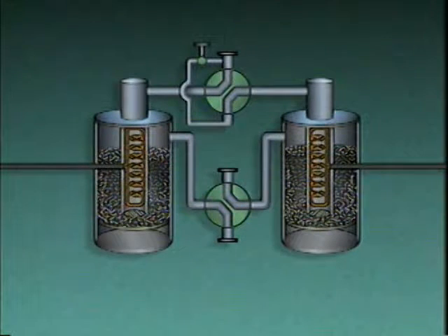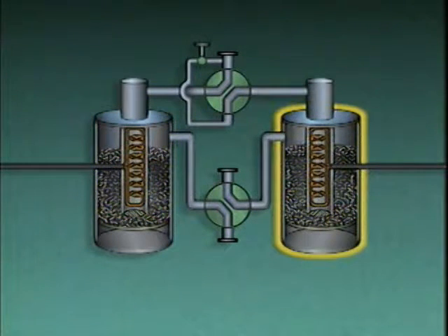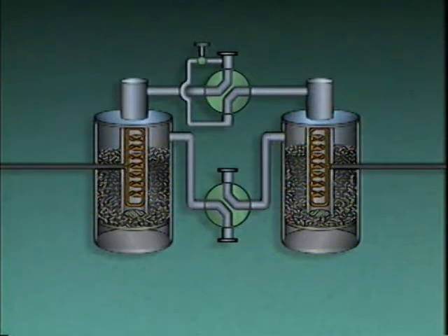At any particular time, one of the two tanks is said to be active. An active tank contains dry desiccant that is used to remove moisture from compressed gas. In the other tank, desiccant is being dried or regenerated. In this example, the dryer is set up so that each tank can either be an active tank or a regeneration tank, depending on the positions of the four-way valves.